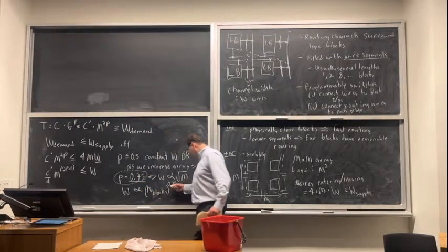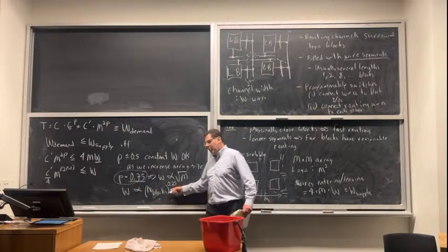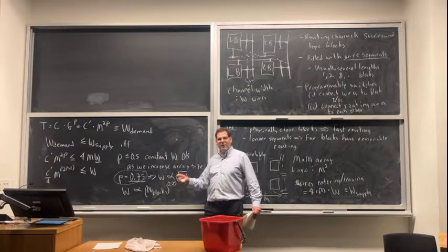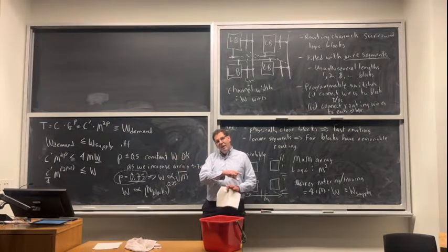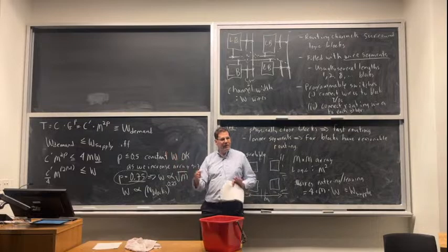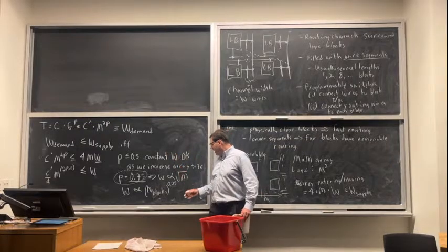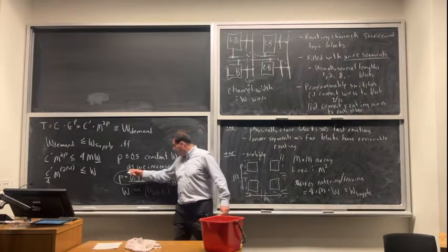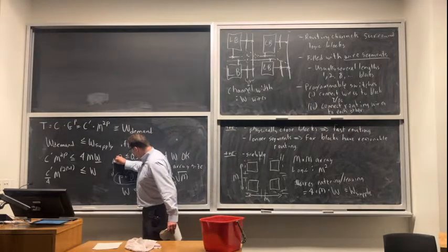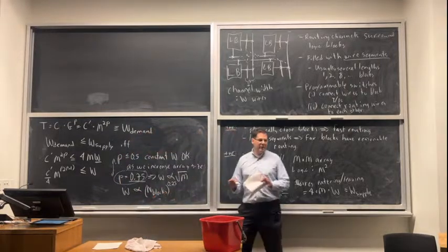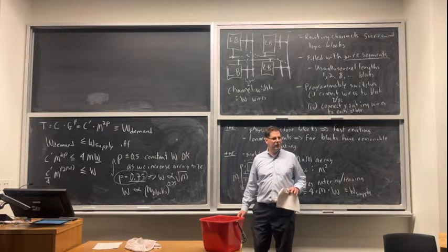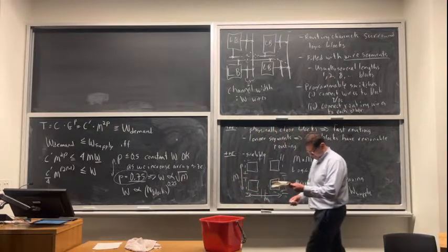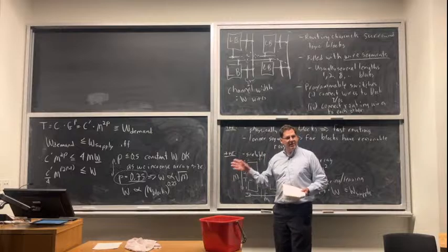So the channels in commercial FPGAs actually grow even more slowly than this. If you track over time, you'll see that the channel width has been slowly increasing as you make bigger and bigger FPGAs. But it's even slower than this because most circuits are kind of in between these two. So the target is probably more like a Rent exponent of 0.6 or so. Does that make sense?